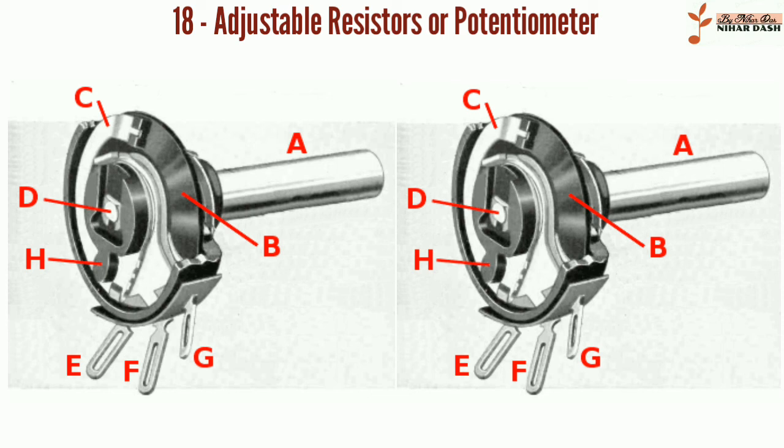A typical low-power potentiometer, see drawing, is constructed of a flat resistance element, B, of carbon composition, metal film, or conductive plastic, with a springy phosphor bronze wiper contact, C, which moves along the surface. An alternate construction is resistance wire wound on a form, with the wiper sliding axially along the coil. These have lower resolution, since as the wiper moves the resistance changes in steps equal to the resistance of a single turn.